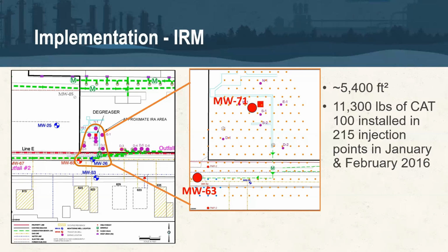And when you're injecting slurries in relatively shallow intervals, we've got to go with relatively low shot volumes to be able to make sure that we're keeping our reagent within our design radius of influence. Because if you start pushing that radius of influence, especially on a shallow site, we've got a lot of utilities. You're going to have a lot of daylighting. You're going to have the material following preferential pathways and not going where we need it to go, right?